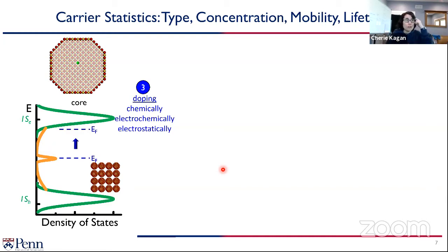And the interesting thing for these kinds of materials, as well as when we teach device physics in class, is that we teach about a perfect single crystal. But whether you have a polycrystalline film, an amorphous film, or nanocrystalline films, the density of states, like I showed you before, looks much more like the depiction here. So there are a lot of similarities between nanocrystal films and amorphous films, even of atomic systems. And so you see some sort of band tail, often referred to as a mobility edge, and a tail that extends into the gap. So you tend to see these systems look like this.